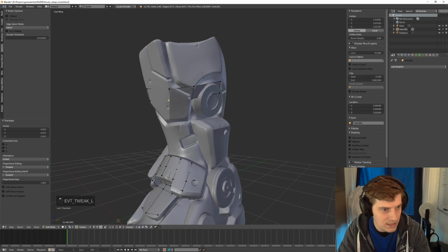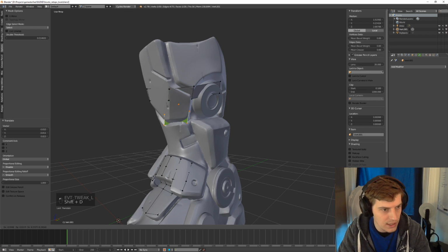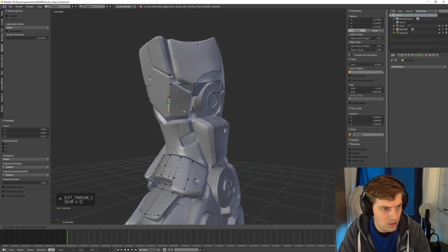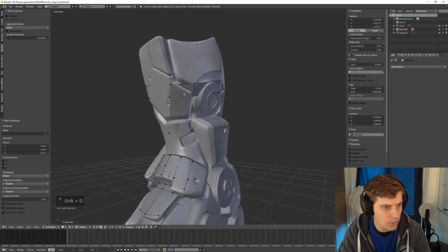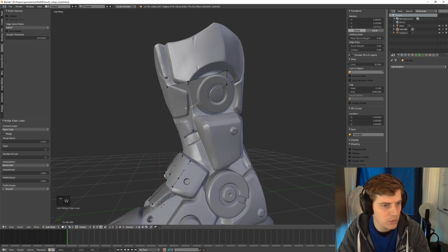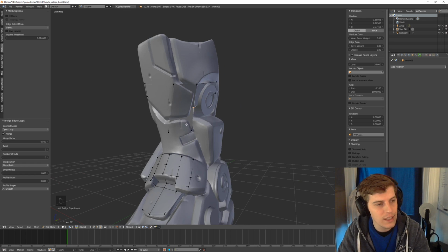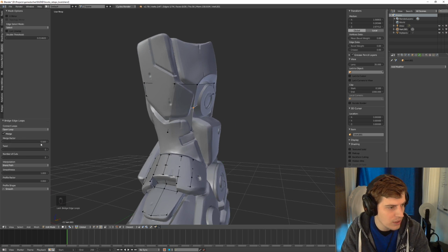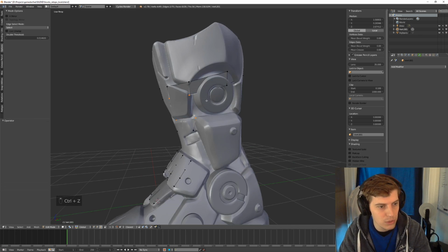And so let's say that I duplicate this one. Oh, another. Okay, there we go. And I want to merge these two together. W, E, and now it's automatically merging. So this is pretty much the fastest way of merging or welding two edges together. One upside is that you still have the option open and you can tweak which edge needs to merge with which edge. So this is a very powerful operation.